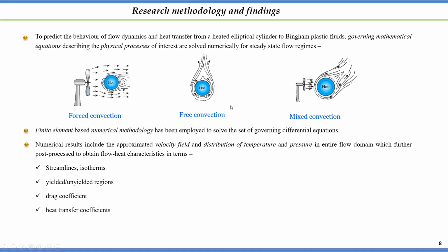And if you combine free convection and forced convection together, then we see mixed convection, where you have an external means to generate the flow. You have natural flow because of the buoyancy difference in this flow media due to the temperature difference, and we see the combination of forced and free convection together.